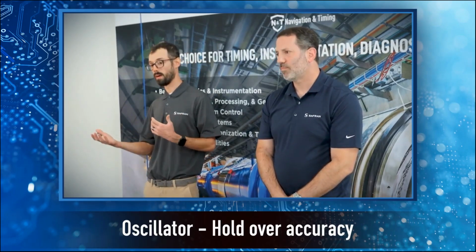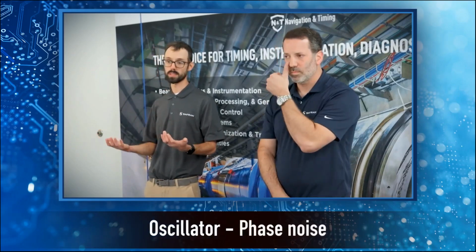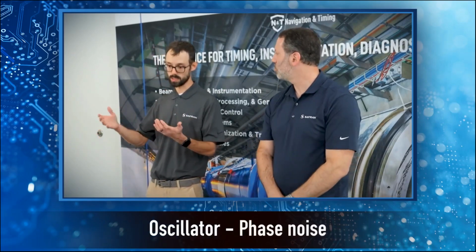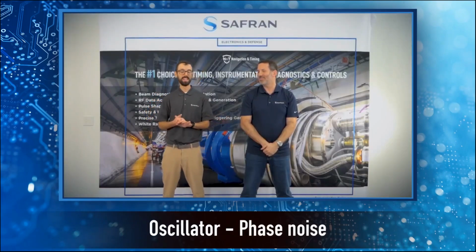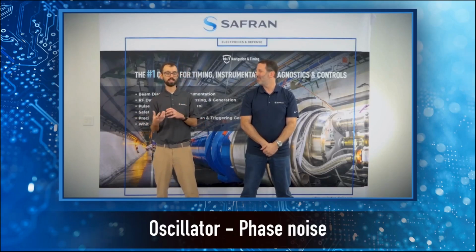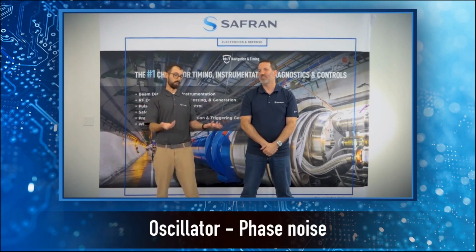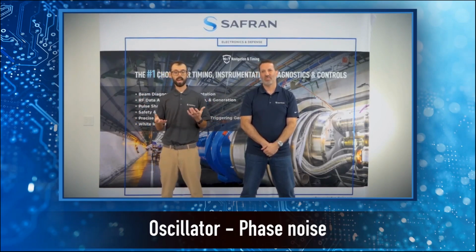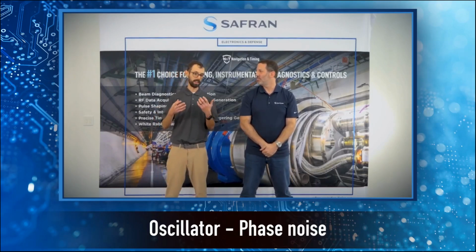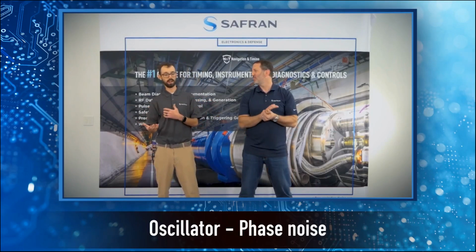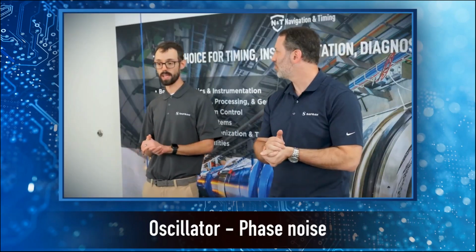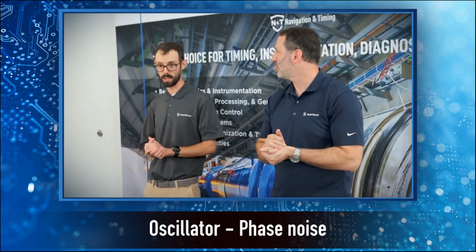And then when we go into talking about low phase noise, those applications will usually know when they need low phase noise. But the low phase noise OCXO actually gets combined with the rubidium to create our rubidium low phase noise option. And in that case, it makes sure that there's not so much of a swing in our frequency or our phase error over time. And I'm sure I probably missed something in there, Dave.